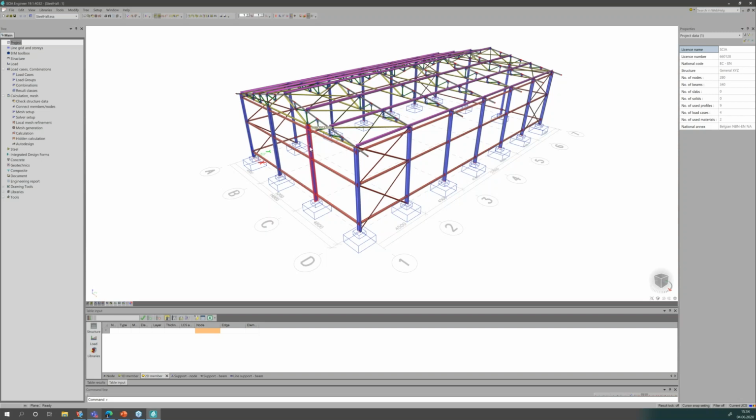What's important to say is that in the case of steel halls or steel structures, you usually model 1D elements like steel columns or some elements of the roof, and you are not modeling 2D elements, but the 3D wind load generator for 3D structures works just with 2D elements in such a case.